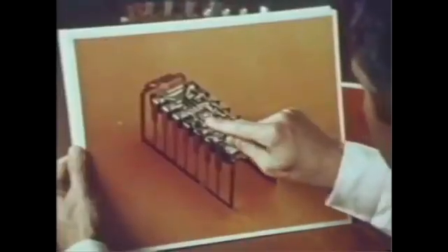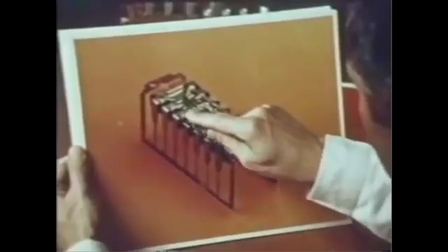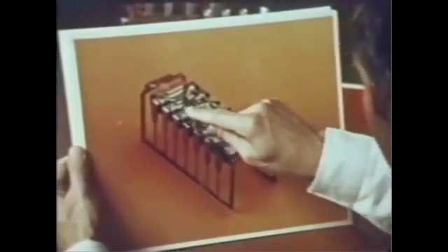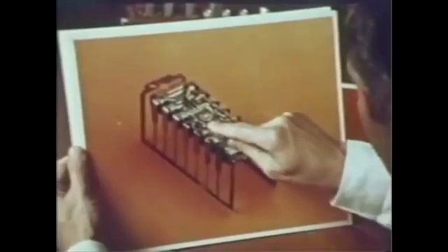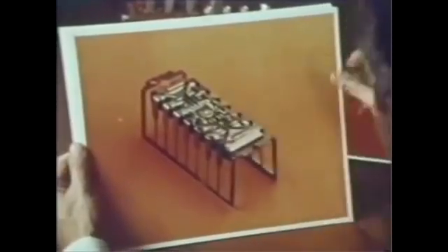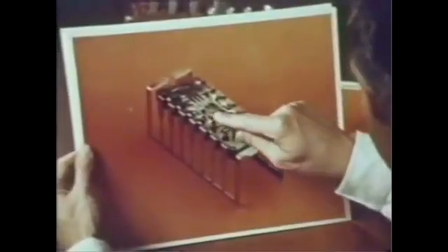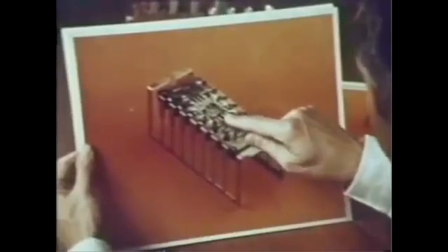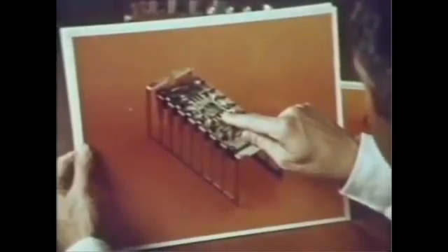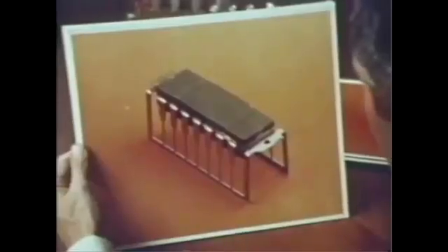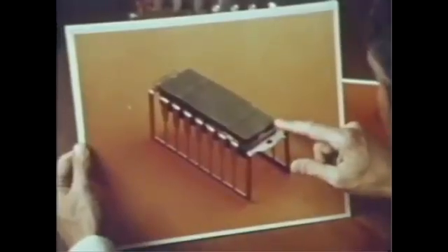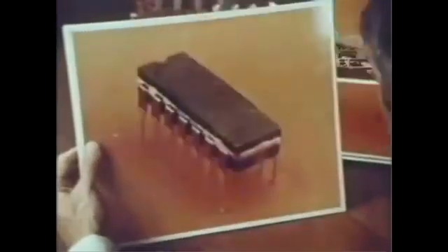And here is the arrangement. Chip in center, Kovar frame around the outside, and notice that the tips of the frame here have been metallized. This will form the connection to the chip directly, as shown here, where the lead bond wires have been placed connecting the pads on the chip to the metallized tips of the Kovar frame. We complete the sandwich by putting the top half of the package right on top of the frame. The next operation will be to clip the ends of the frame.